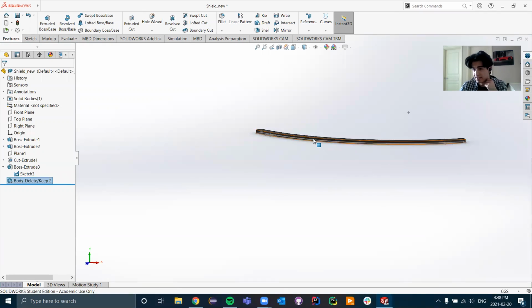It just essentially deletes everything around it, which is perfect. Now, usually you don't want to do this. Usually you don't want to have the remnants of your other part within this part and essentially have the new dimensions of your current part reference those old dimensions. The better way to do it would be with mathematical expressions. But for the purpose of this tutorial, what we've done is essentially just copied it over.